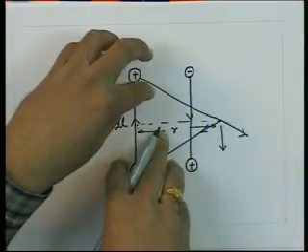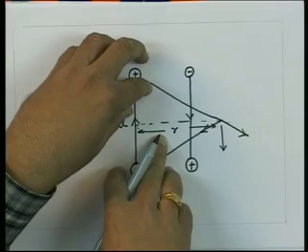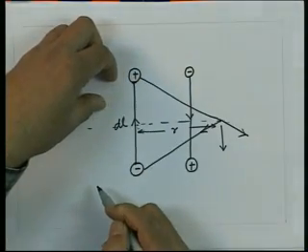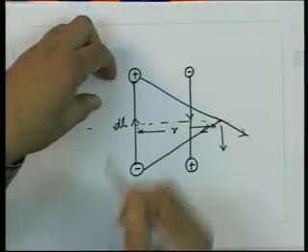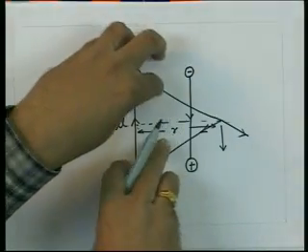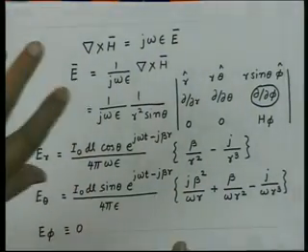So, as the frequency becomes smaller and smaller, the amount of charge which will get accumulated on the ends of the Hertz dipole will go on increasing, and when you go to a frequency which is DC, the current will always be flowing upwards, and in the steady state these charges will go to infinity. So, as the frequency goes to 0, this field essentially blows up to infinity, because in steady state there will be infinite charges resting on the 2 ends of this dipole.